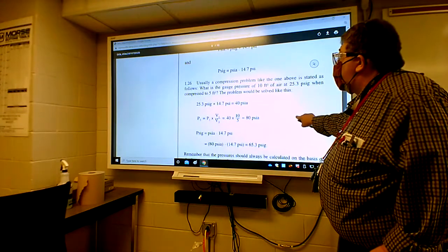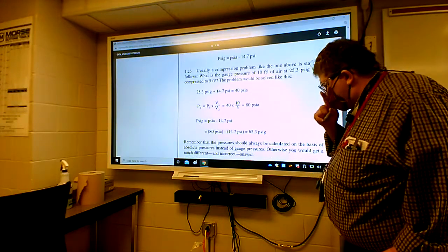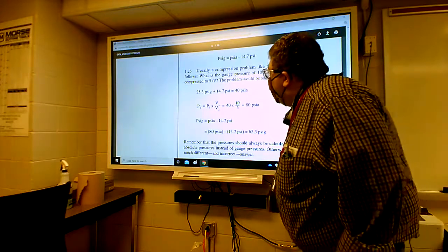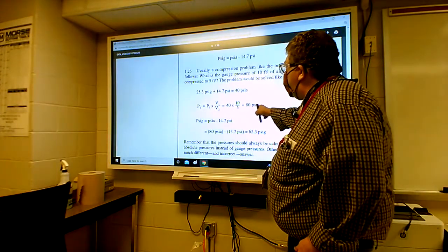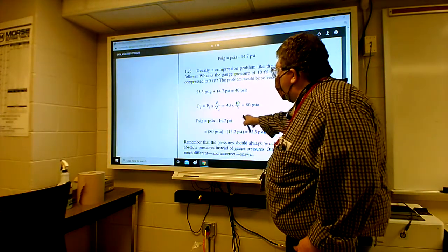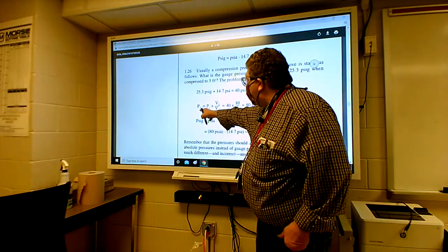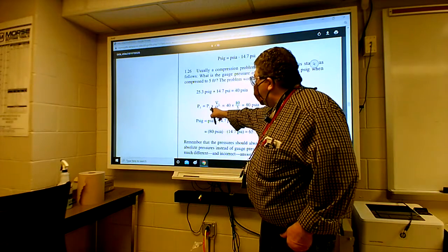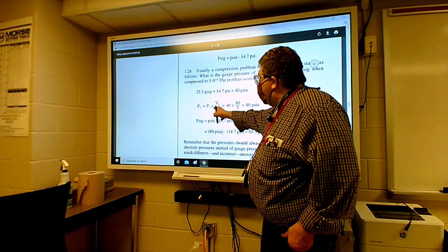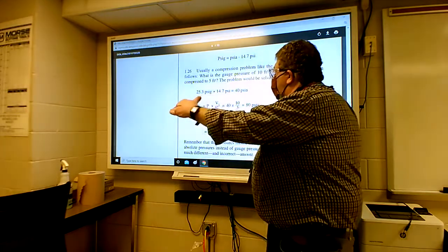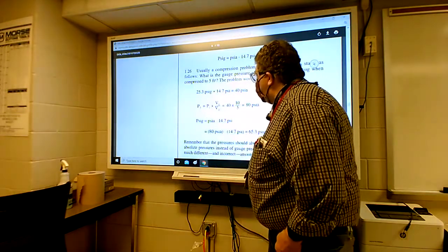So you take the 40 PSI there, and if you're going to calculate the final pressure, the equation would be that P2, your final pressure, would be P1, pressure 1, times the ratio of volume 1 divided by volume 2.